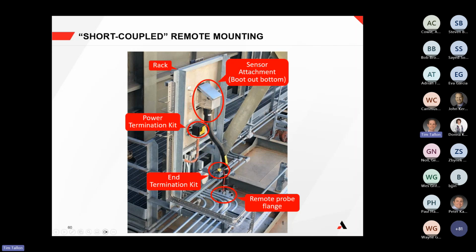Good point. So, Tim, there was one question on the heated sample line. It asks: when using a remote mount, what size tubing in the heated sample line is used between the sample point and the analyzer? Is it 2 tubes? So I don't know if you guys are going to discuss the heated sample line a bit, but there's a question around that. Yeah, well, we can talk about this later, but we can answer right now. So the quick answer is we recommend 3/8 inch tubing.